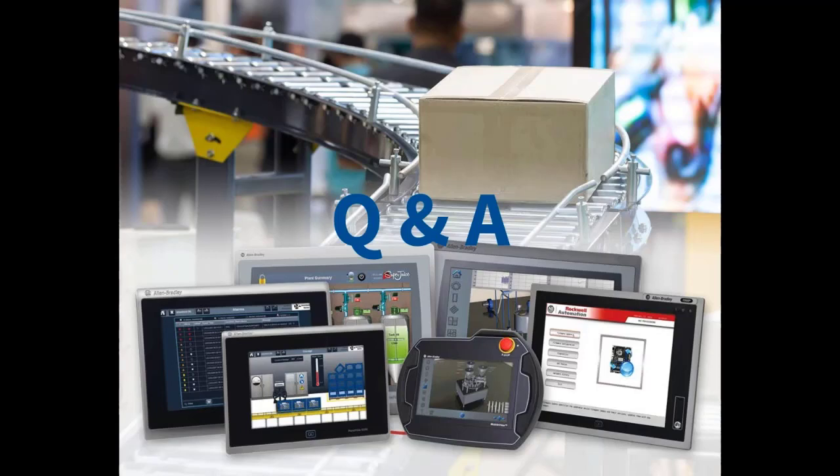Perfect. And we will move on to questions for Mr. Pelton. If I'm running my PanelView MER on the Windows computer, how do I update the firmware on it? Is it like the Series B flash? So this would be a little different than with the PanelView Pluses. Because this is a Windows 10 operating system, you're actually going to be installing FactoryTalk View ME Station.